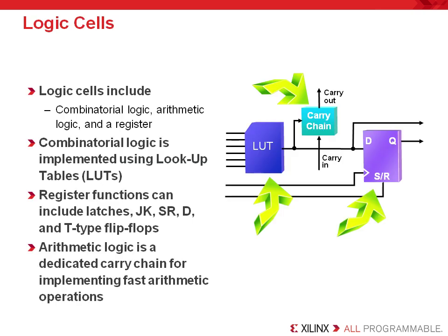The logic cell is considered a standard benchmark in the FPGA industry. Each logic cell is essentially a single LUT with an associated register and is considered the fundamental building block of your design. As we have already mentioned, each Xilinx device contains an array of CLBs.